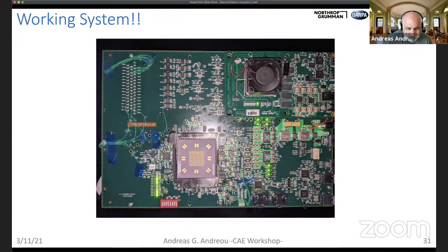Here is the test board with the chips. This is really our test environment. We can say now we have our chiplets working. They're packaged and tested on this test board. The NOCs and the processors are running at 200 megahertz for these chips. And we can perform multiply-accumulate, measured, not estimated, at about 25 femtojoules per op. We simulated 22, and we actually measured 25 femtojoules per op, which gives you something of the order of teraops per milliwatt. So this is an extremely efficient chip.